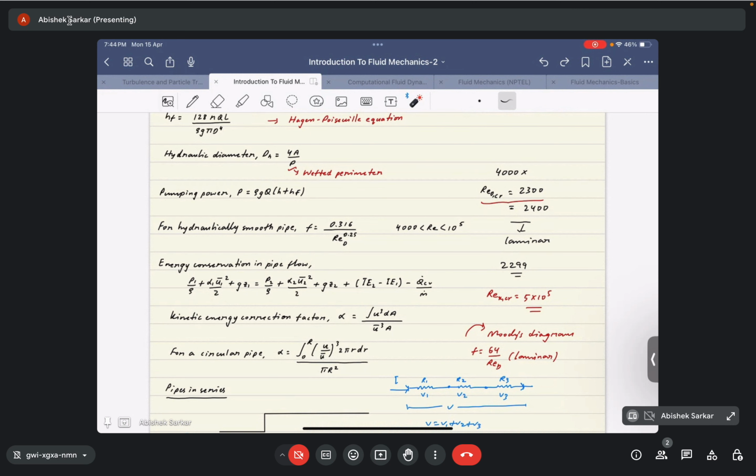Here they have given a formula for a hydraulically smooth pipe, so for turbulent flows as well we have a formula for the friction factor. But the usual practice is to take the aid of the Moody diagram to find the value of the friction factor in the case of turbulent flows. Since they already mentioned the formula here, you can use that, but the more ideal practice is to use the Moody diagram. We have not discussed that here, but it is something you can look into.